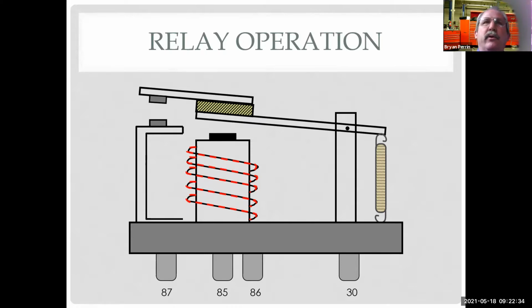Okay. So we don't use a GFI on cars because we're DC instead of AC. But what I would do is run a fused circuit going to 30. I can also branch off that fused circuit and go over to 86 with it because I can feed power into both of these. I could run a wire from inside to ground off a toggle switch or whatever to turn it on, and then this is going to go out to my vehicle. So now I have a fused circuit with a dedicated fuse going all the way back to the battery, so I'm not going to overload anything.